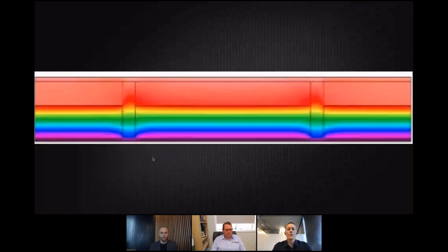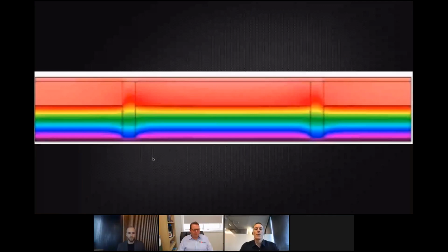So the value of the wall here is about 70% of the sticker R value, meaning what's stamped on the bag when it arrives on site. It's called effective insulation or construction R value, as Alex has touched on. It's the value of the insulation after you've subtracted the missing insulation. But it doesn't stop there.